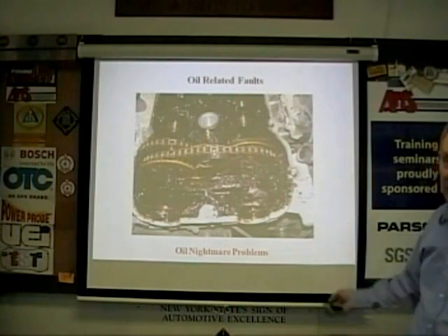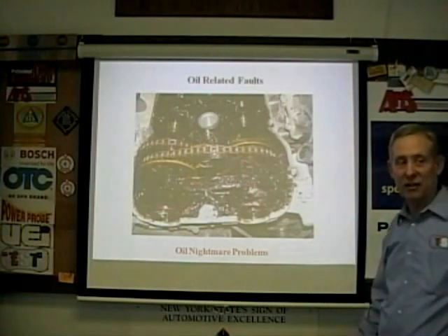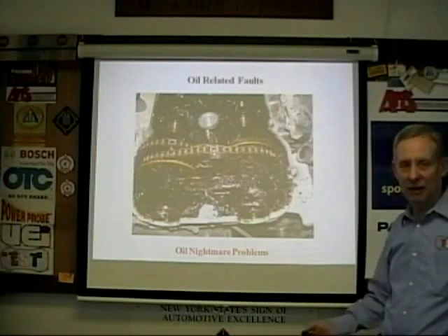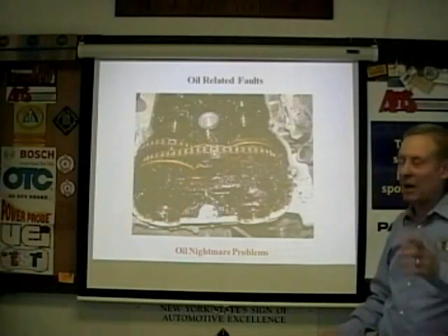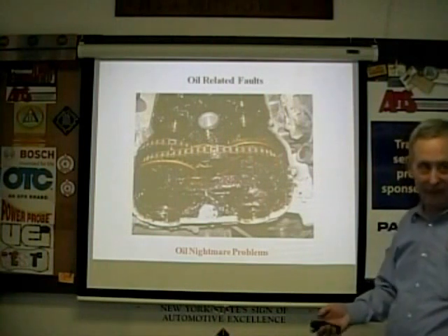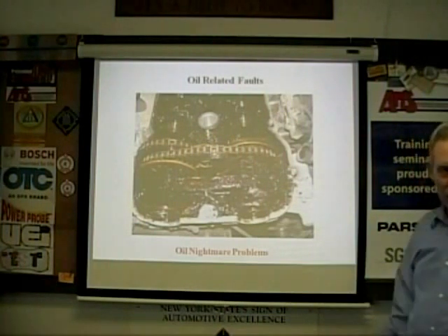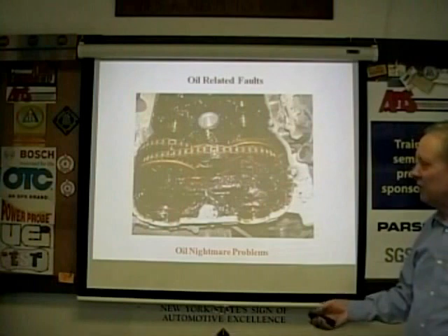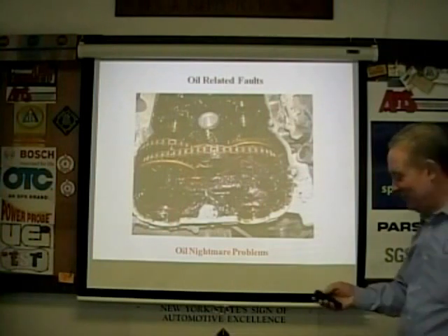It would chatter and it would actually cause the timing retard. The knock sensor would hear it and pull timing back till the car ran like a total pig. That's similar to the Porsche setup as well. Right. Yeah, they all went to the same university.